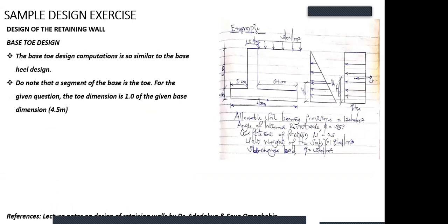So basically for our toe, we follow the same precedent, but now our toe only has the vertical base. So the remaining will be what? Our base pressure. And our base pressure here, don't forget, I'm supposed to draw this to take the pressure distribution. We are pretty sure that at that center, from interpolation, we get what? 115. 115 acting at that center. So 115 acting at that center times 1.2.